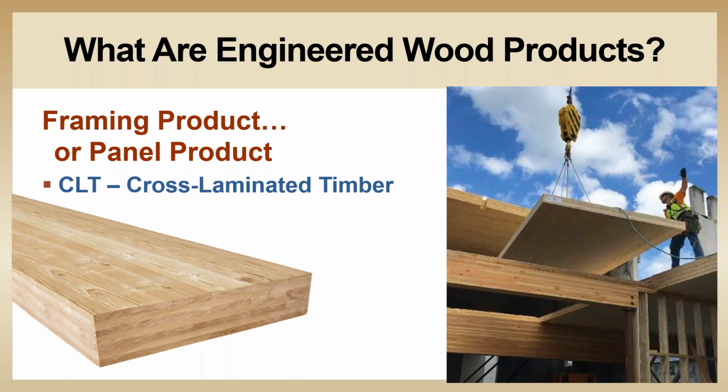Using CLT for lateral load resistance is going to typically require the engineer to use the alternate means route provided in the IBC code, or the recently added 2021 SDPWS sections 4.5 and 4.6. You'll also sometimes see engineers use other materials on top of CLT, and this can be like using OSB or plywood, and this is to get the roof or floor diaphragm capacity that they need.